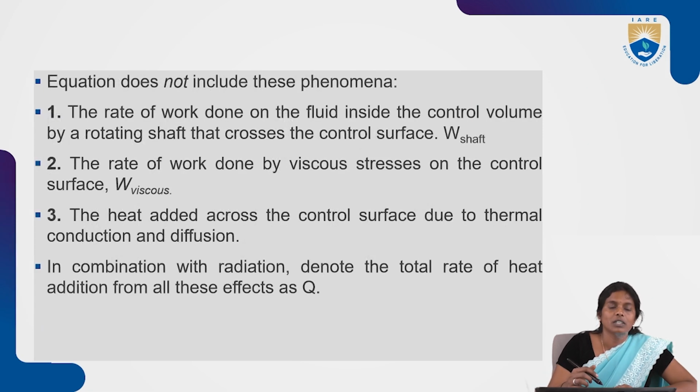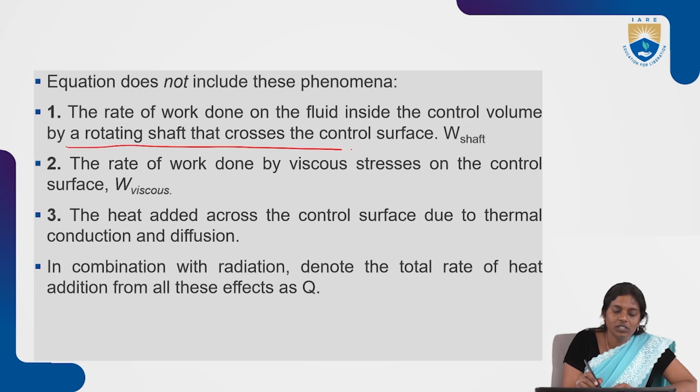Now, the equation which we have seen does not include the rate of work done on the fluid inside the control volume by a rotating shaft that crosses the control surface, that is W shaft, the work done on the shaft. We are not considering that. Then the rate of work done by viscous stresses on the control surfaces, W viscous, we have also not considered. Then the heat added across the control surface due to thermal conduction and diffusion, we have also not included in the equation.